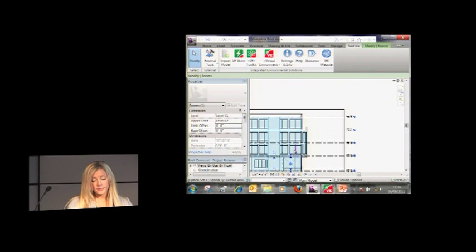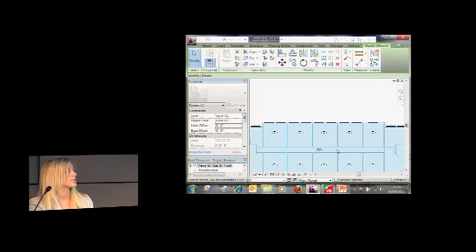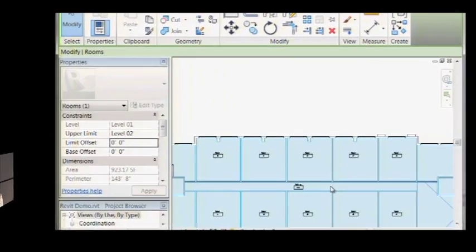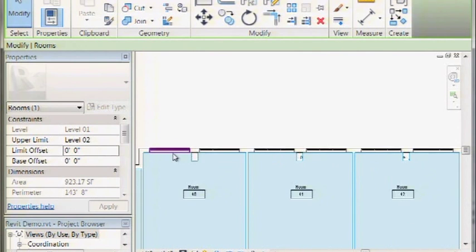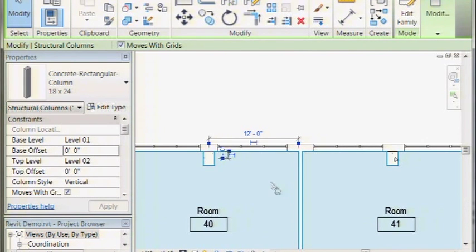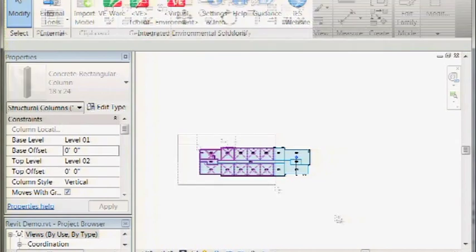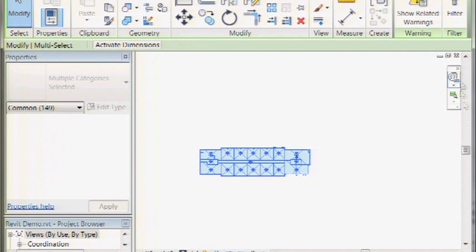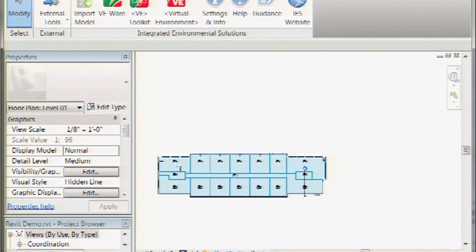So again, with the varying size walls, sometimes with your models, if I get them, I will just try to highlight all the interior walls and change them to the same. It doesn't usually work so well because it'll gap the walls sometimes, but it is a way to start cleaning it up. Also, here the column issue. You can select the type and edit the type to be non-room bounding, or you can just select in a view using a filter, which is probably my best option, which is actually over here, but we can't see it due to issues with resolution. That's definitely a way to fix it.